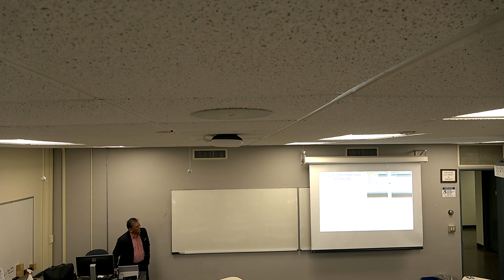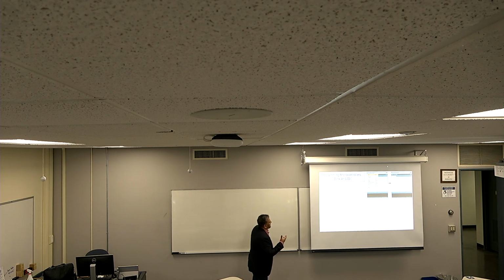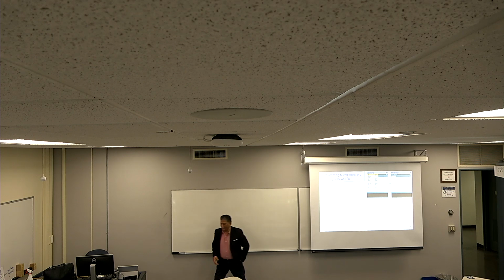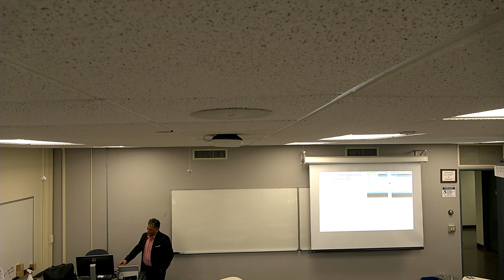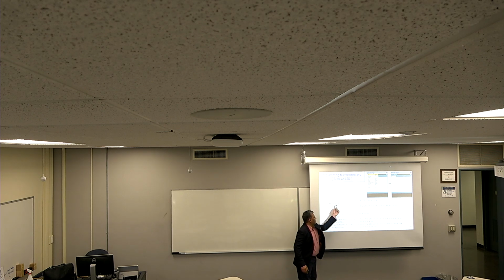So anyhow, how do we do it? We had the prototype circuit built. This is the IDE, how the Arduino IDE looks, for whoever has experience. I'm going to run it from the machine I'm using, and here's the program I wrote. Again, setup only runs once, so I'm setting pin 13, the mode, as an output.